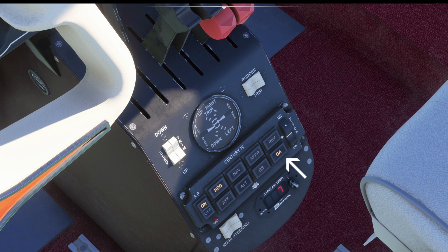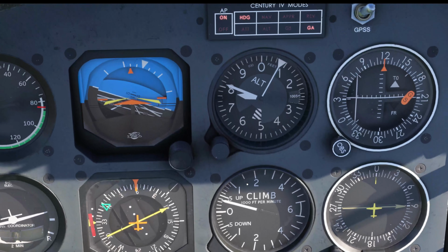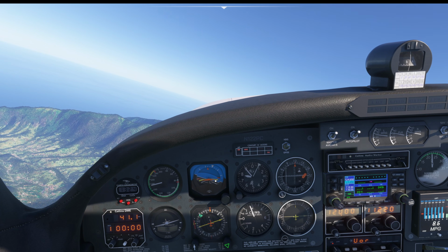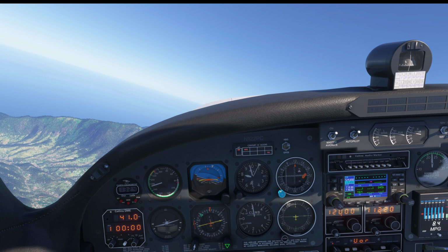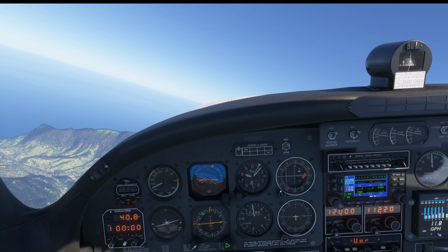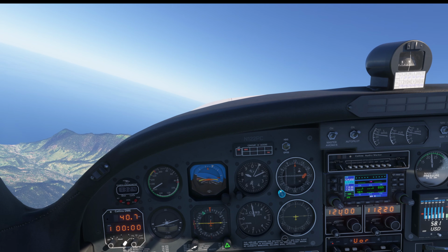Go around mode is just like the pitch mode, except it commands a predefined pitch angle. This mode can be used not only in go around situations, but also in cruise when you want to command a moderate climb.